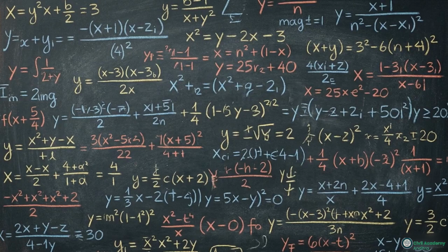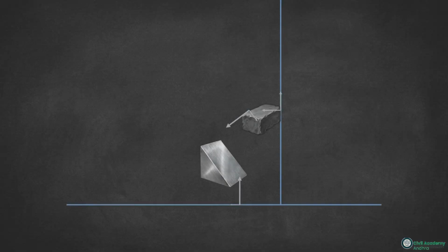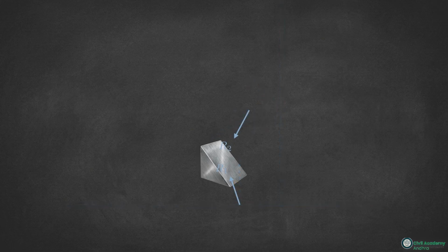Because each surface requires x and y equations, this method creates a gridlock of simultaneous equations, highly prone to calculation errors. We can bypass this by applying our angle of friction. If we delete the orthogonal components entirely, we can replace them with single resultant forces, each offset by the angle of friction from its normal plane. Now, if we isolate the wedge from the surrounding environment, the complexity of the force state disappears. We are left with the horizontal pushing force and two resultant vectors.